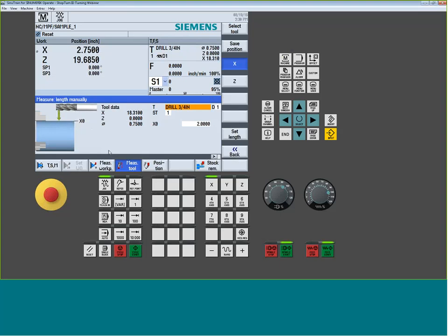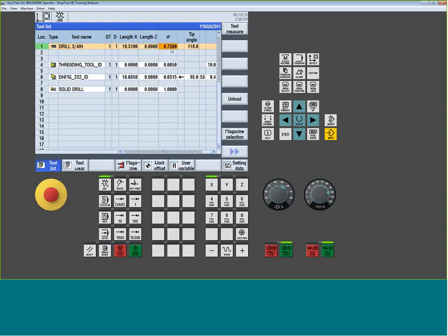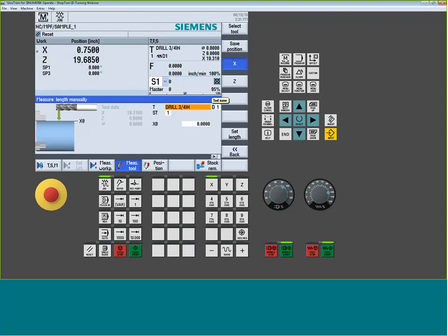But again, if I want to bring her down and have everything lined up with center, so maybe I was expecting to put 0 in, because everything's indicated, everything's perfectly lined up, my tool's sitting down here on center line. You see, it still tells me, no, you're 750 away. We're compensating for the diameter of the tool. So what you're going to do is 0 out the diameter. You don't have to call up the tool. We reload offsets on the fly immediately.